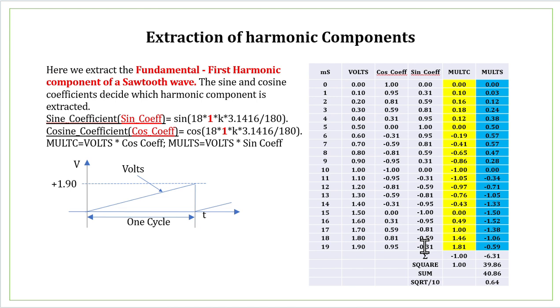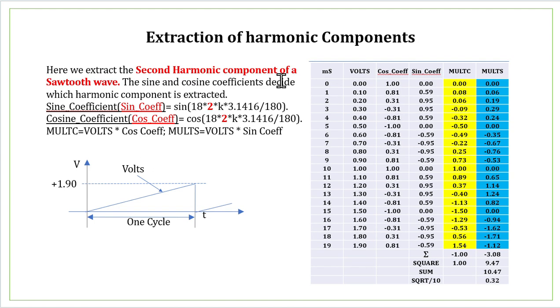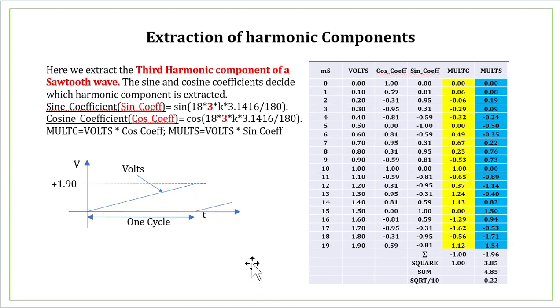Okay. Now this has got harmonic, second harmonic. It will also have second harmonic. So this kind of waveform has fundamental, first, second, third, all the harmonics. First you have seen. Have a look at the second harmonic. Procedure is the same, and you get 0.32. Then we go to the last one. Here procedure is the same, and you get 0.22, and you are calculating third harmonic.